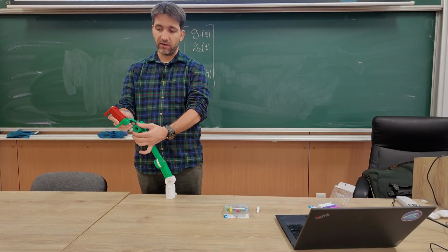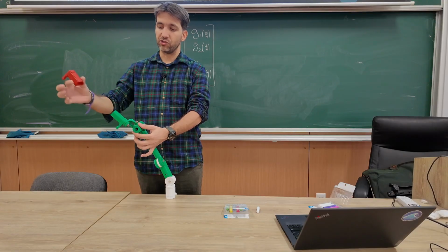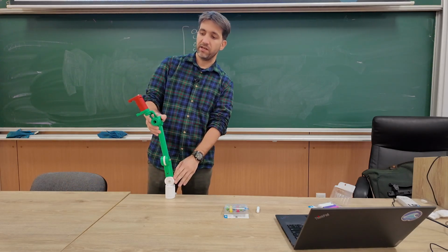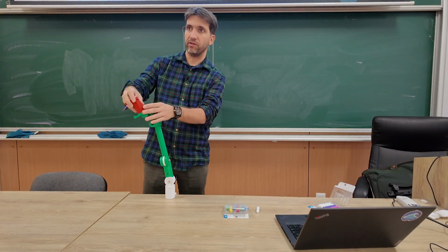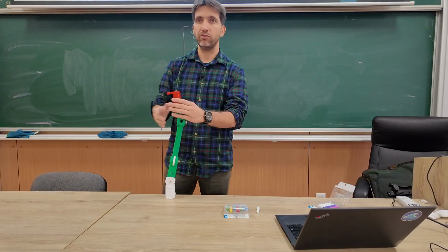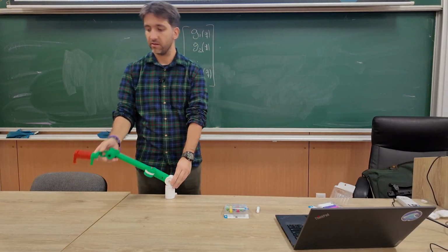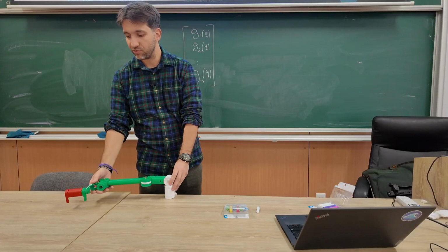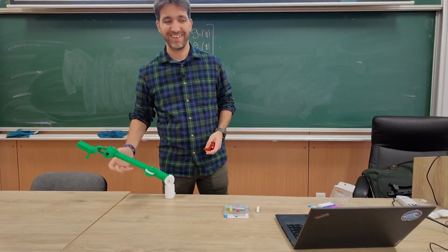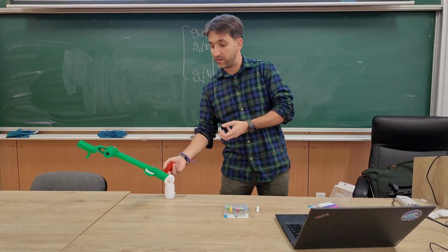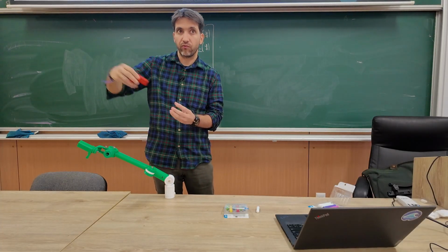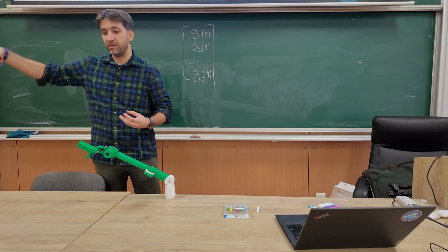So I'll try to demonstrate here with this joint, basically the prismatic joint. Can you imagine that if this joint rotates, then this generates some centrifugal motion for this joint, the prismatic one, right? So when I rotate this very fast, you saw that this thing got extended, right? I have to do it not too fast, not too slow. But that's basically it, right? When I rotate this one at some velocity, on any velocity, it generates some force pulling out this piece, right?